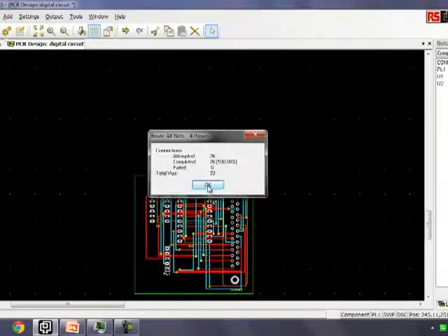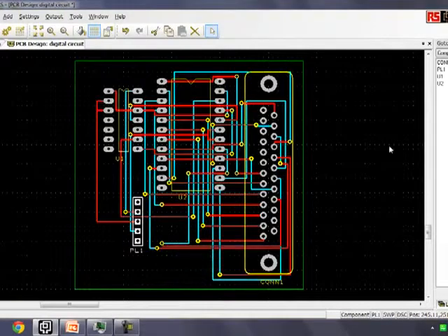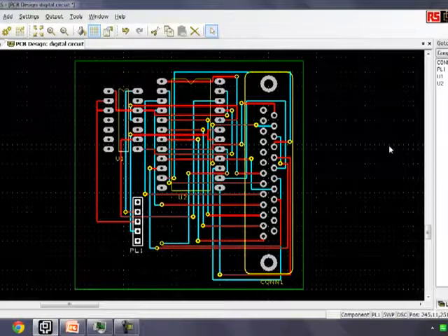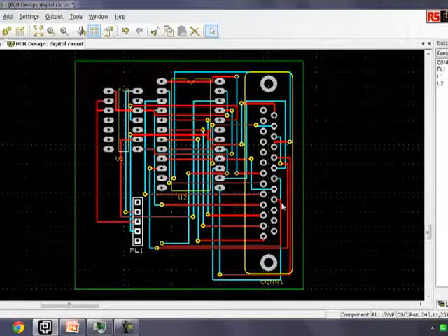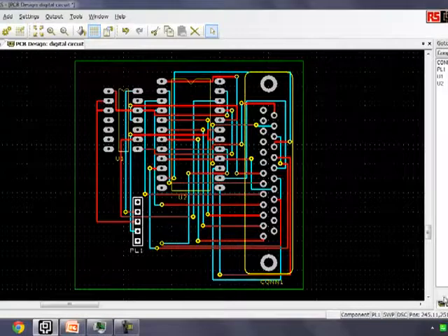Okay, so just zoom in on this. So basically what we have, very quickly and very crudely, is a basic PCB layout. Here you can see a number of the colours: red for the top copper and blue for underneath. Now, using the interaction bar by pressing F9, which I'd already done, you can go to the layers.